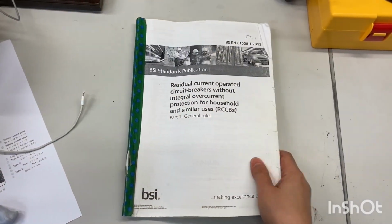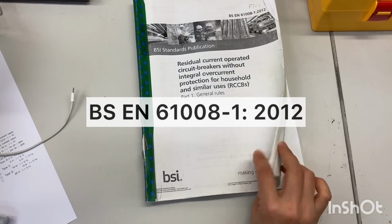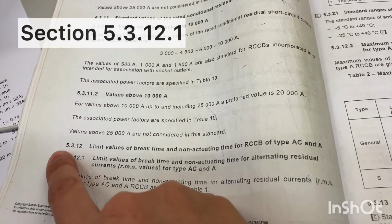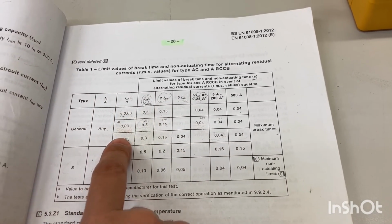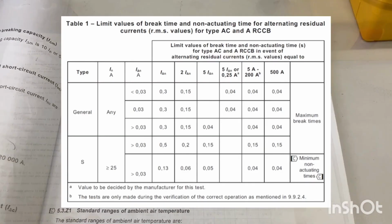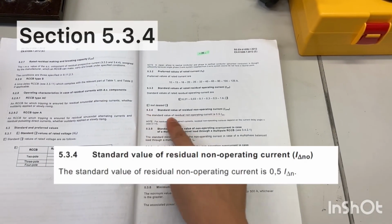After collecting all the data, you have to refer to the British standard BS EN 61008-1 to check if the performance of the RCD has complied with the requirements. You may refer to Table 1 of Section 5.3.12 and also Section 5.3.4.